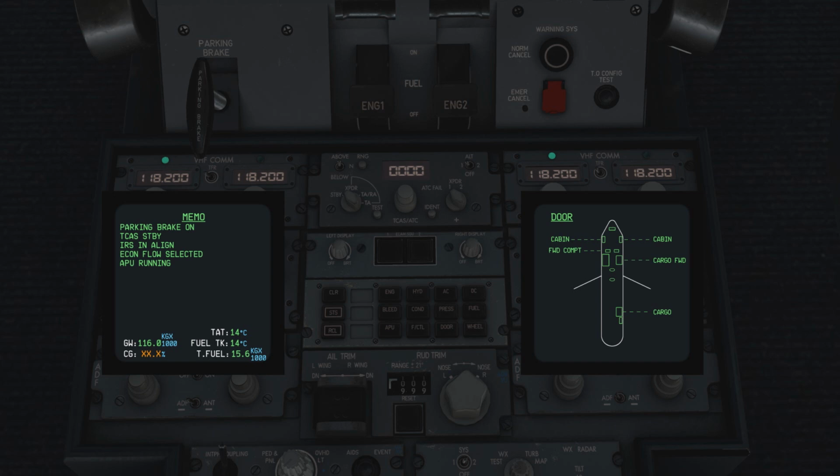What are we looking at in front of us right now? This small panel, so here, this one, is called the Ecam control panel. We've mentioned it already. What does it do? Let's not get too far ahead of ourselves, let's look at everything else we've got around here. Here it's just a display brightness for the displays, and these are the signal generator units that when you turn them off, they actually will blank the Ecam screens and the SD page screens because the signals can't be generated. It's a bit too advanced, so let's just stick with the basic functionality for today, but feel free to play around with them, they should work as advertised.